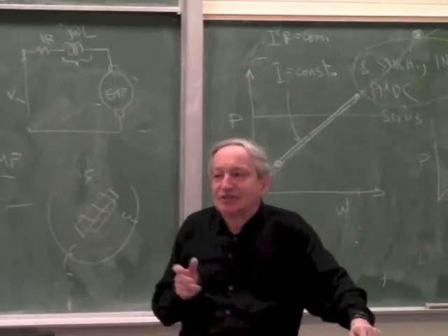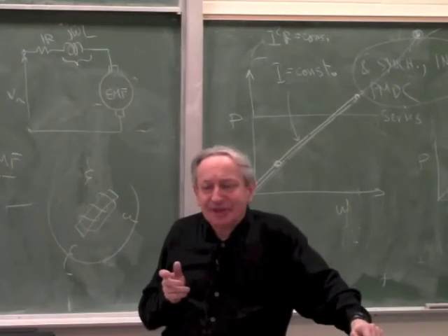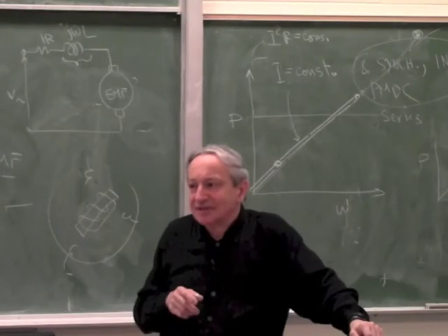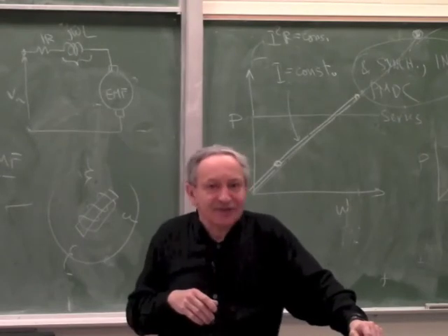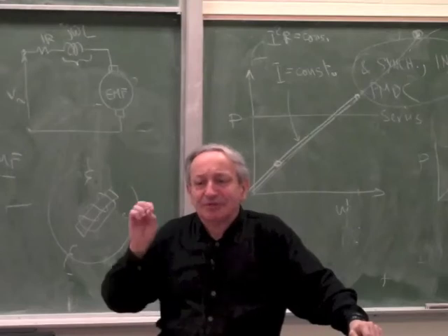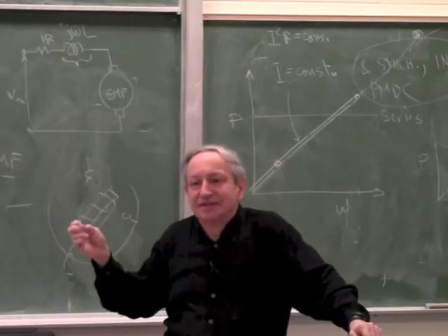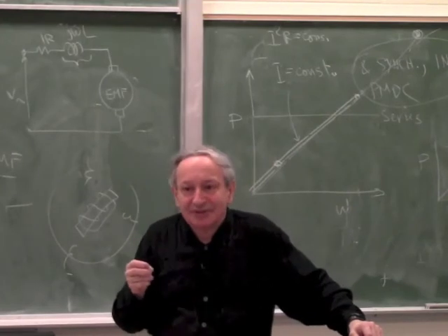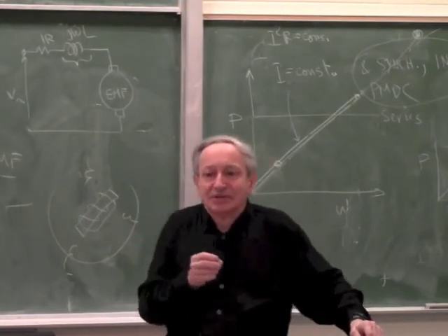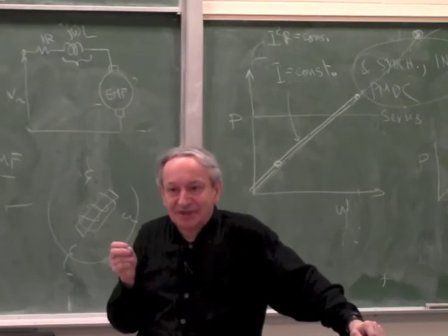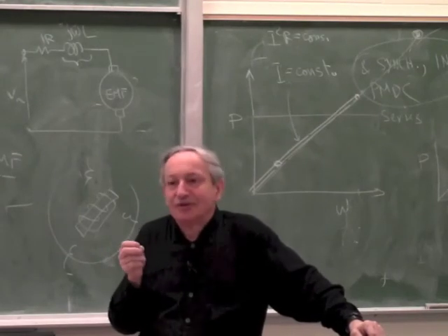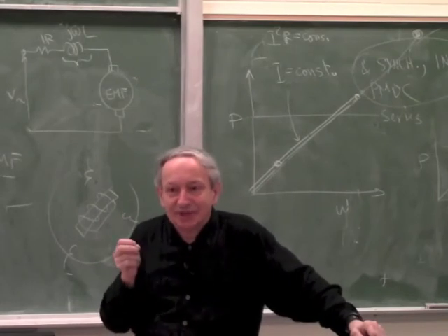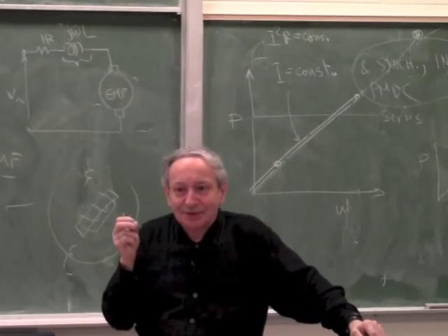The only side effect is noise. The bearings are not a big issue. You can use ceramic bearings, which Tesla uses, and you basically get infinite life. So the real issue becomes noise. It makes a whine. Like 60 hertz is very low, not an annoying noise. But if you run a motor at 60,000 RPM, which means 1,000 hertz, you'll get a very annoying whine. Like if you go to a dentist, the dentist drill is 200,000 RPM. And nobody seems to like that noise.